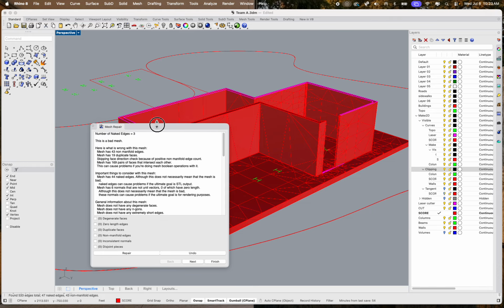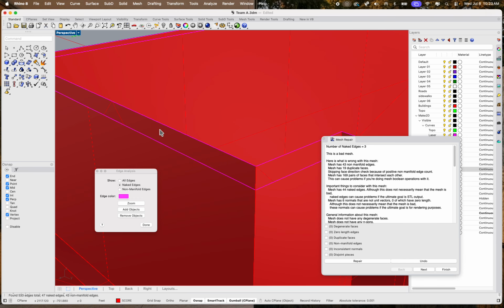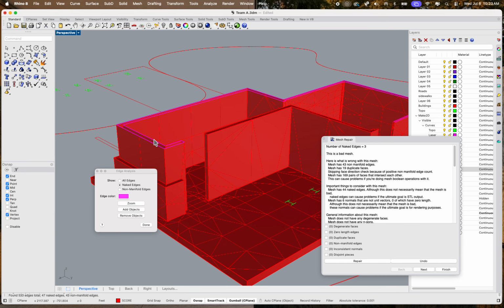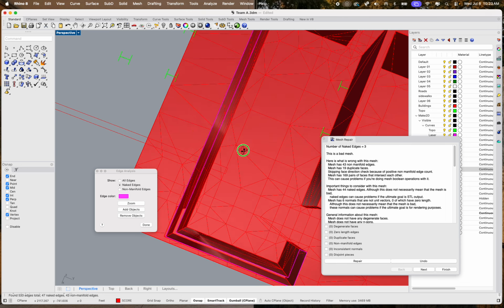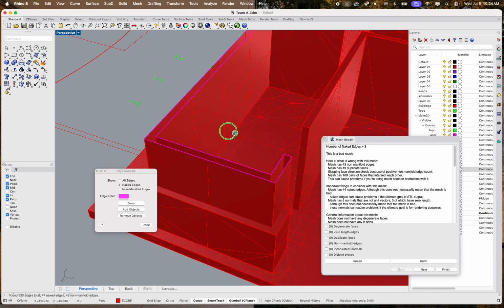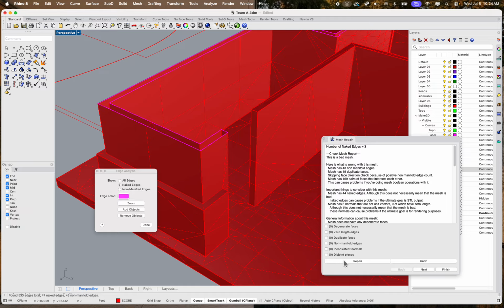Now it'll actually show and start to indicate what is wrong with it. So for instance, it's revealing that open edge, right? It's still actually reading as an open edge, and it's quite revealing, right? Especially when we did the Boolean union, it was like, hey, I don't know what to do with this, and we have an opening. So in my case, sometimes I can actually close these things. So usually I check all these. Even though they say 0 right now, I'll still usually hit repair, repair again, until basically it's a good mesh. However, as you can see, it's not going to fix that piece.